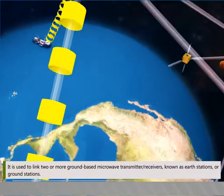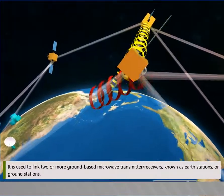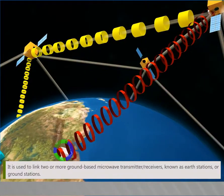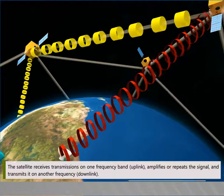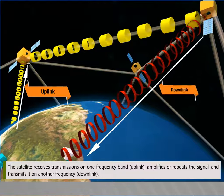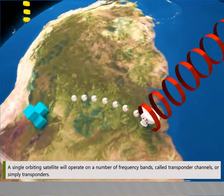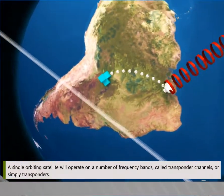It is used to link two or more ground-based microwave transmitter or receivers known as earth stations or ground stations. The satellite receives transmissions on one frequency band, that is uplink, amplifies or repeats the signal, and transmits it on another frequency, that is downlink. A single orbiting satellite will operate on a number of frequency bands called transponder channels or simply transponders.